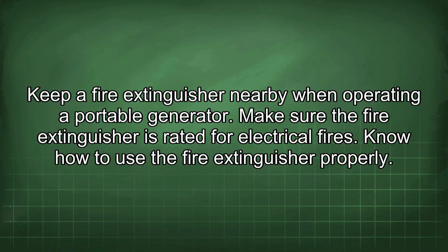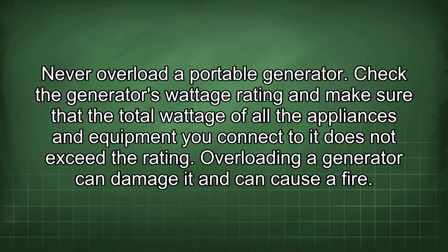Keep a fire extinguisher nearby when operating a portable generator. Make sure the fire extinguisher is rated for electrical fires. Know how to use the fire extinguisher properly. Never overload a portable generator.